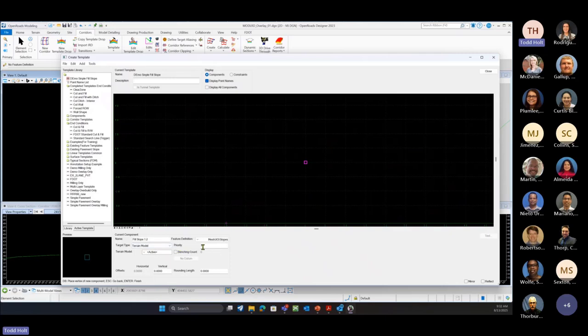And then we're going to set the priority. We're just going to set that to 1. When we have branching of end conditions, or different solutions for that end condition, we set different priorities. What do we want it to solve for first, second, and third, and so on? That's going to be with our priorities, and we'll go through setting these up. It's just a number for the order in which we want it to solve. It could be 1, it could be 10.